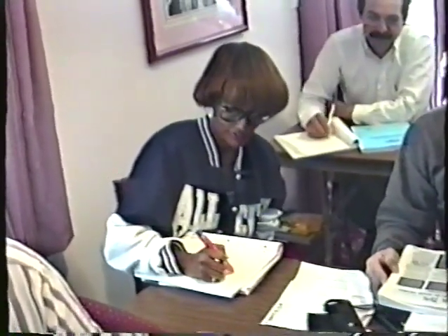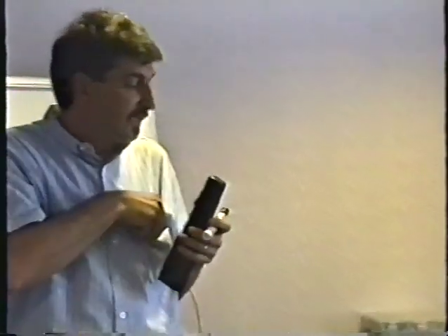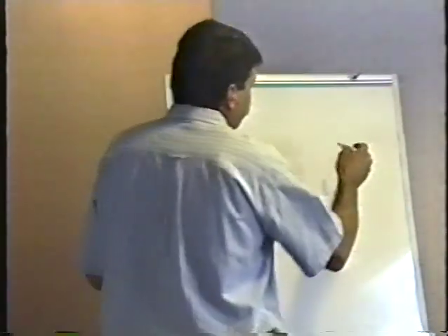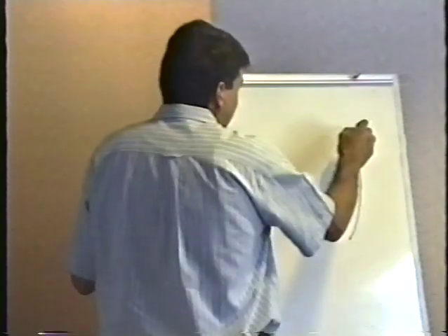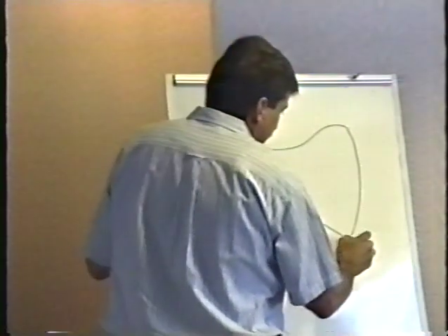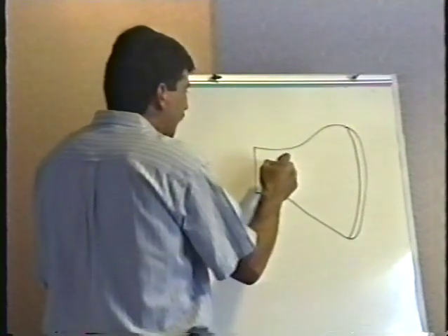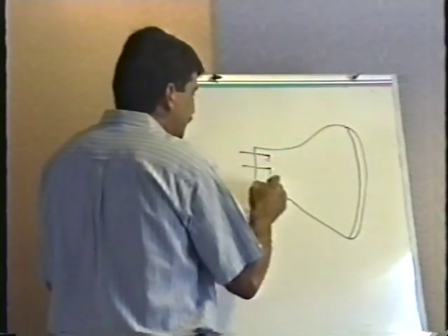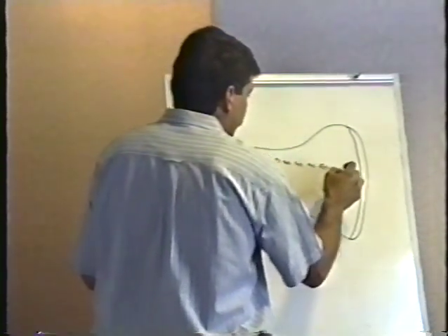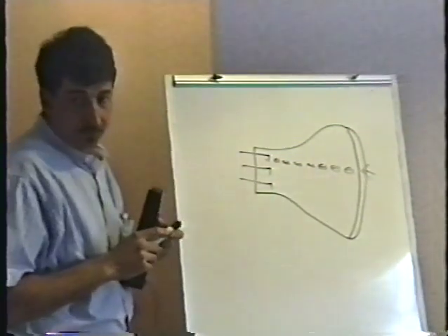We still have to look at one more thing before we can truly understand how the monitor works. Let's go back to the picture tube itself. And remember, the picture tube's made out of glass. It's got this nice thick glass front on it. The 3 electron guns down here shoot out these beams of electrons. The electrons strike the front of the screen and they make the phosphor glow.